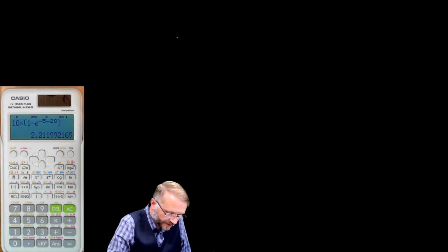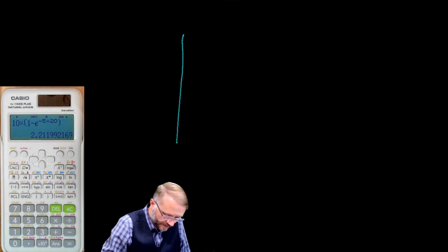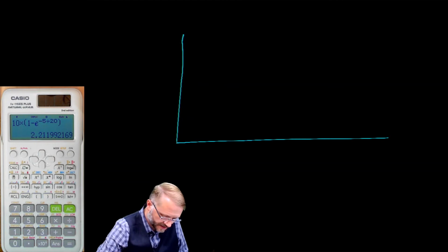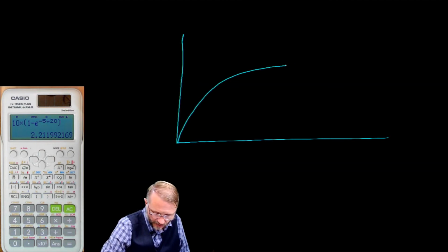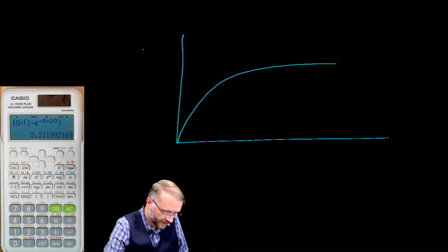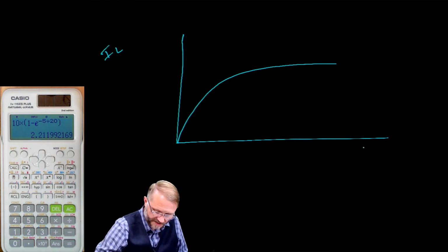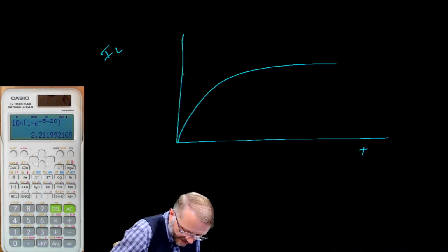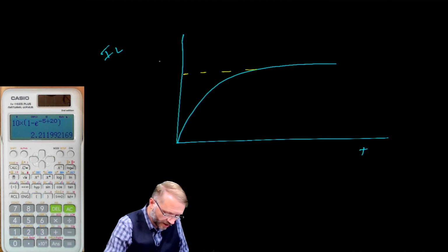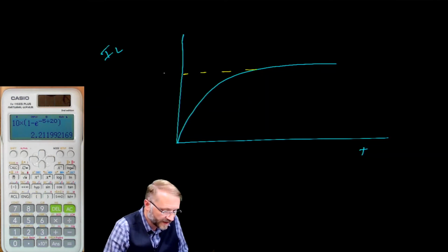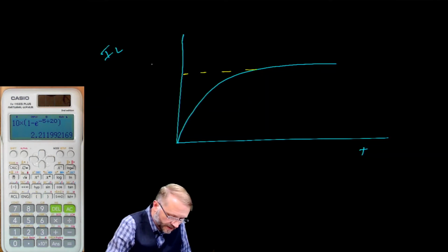We could make similar curves for inductors, except this time it's not a question of voltage, it's a question of current. So this is inductor current, and this is time. We will find that the inductor will have a maximum current of the source voltage divided by the resistance.